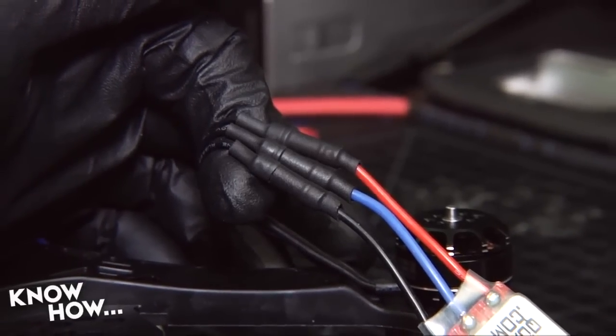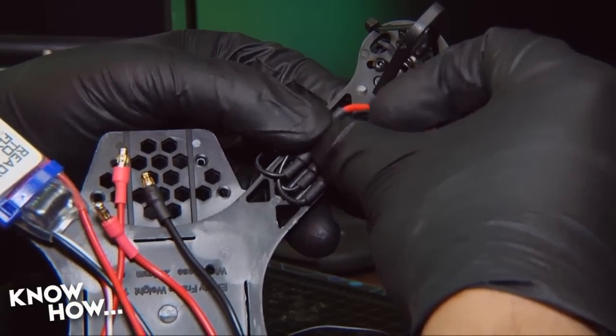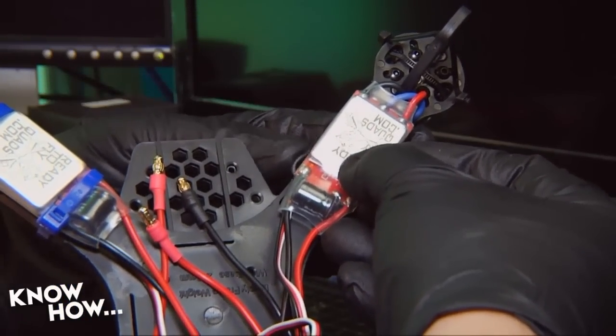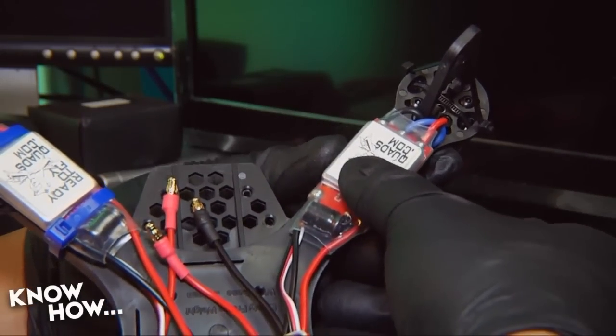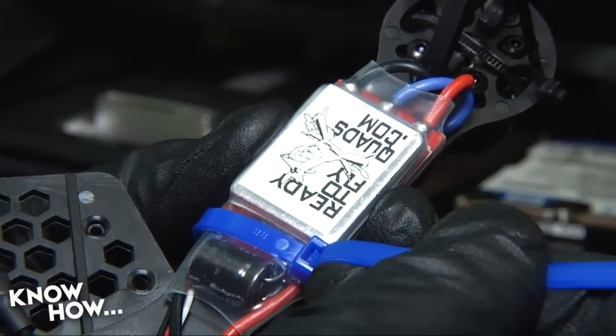With all your ESC and motor connectors soldered, run your wires down the side of the arm. Notice that there's a small indent in the underside of each arm. This is where your excess wire and connectors will go. Position the ESC over the cables in the indent, then use zip ties to loosely hold the ESCs in place.